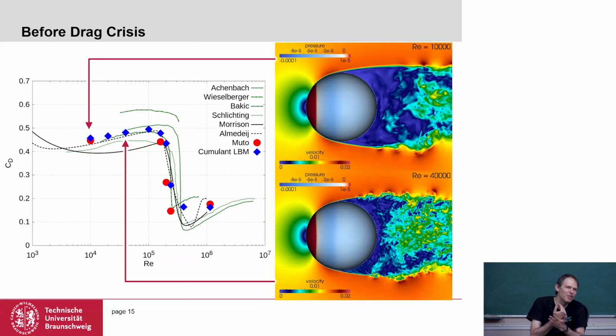were actually first able to use a Cartesian grid. On a Cartesian grid, we can resolve the drag crisis. Basically, you could say that we can do this with OpenFOAM too, but OpenFOAM uses a body-fitted mesh with extended elements.